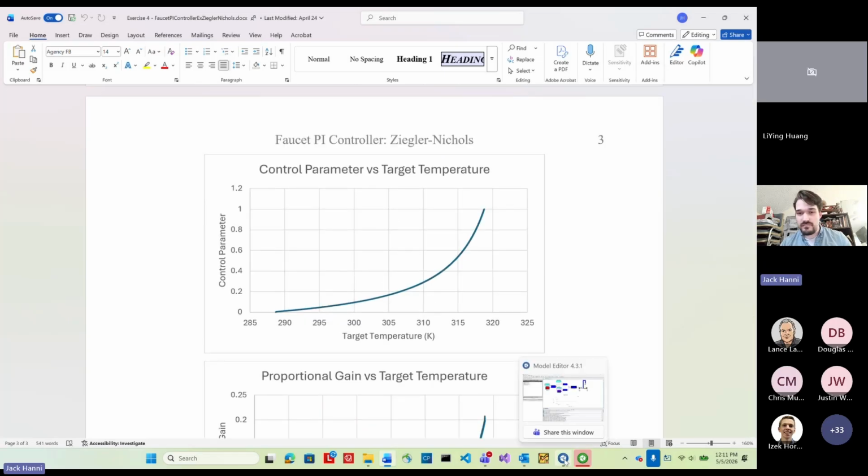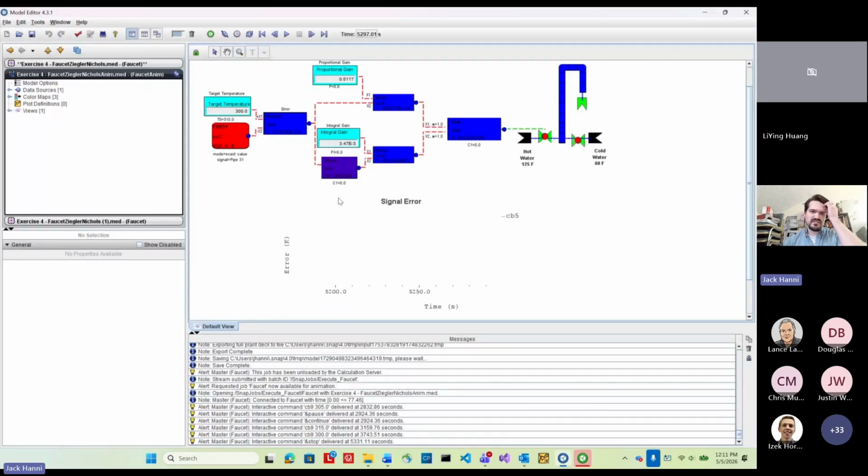But yeah, so that's how Ziegler-Nichols works. It's nice because it's completely empirical, so there's not a whole lot of analysis or computation that needs to happen beforehand. But it does take a little bit of time to get the right max proportional gain, especially if you don't have an easily adjusted model like this one.